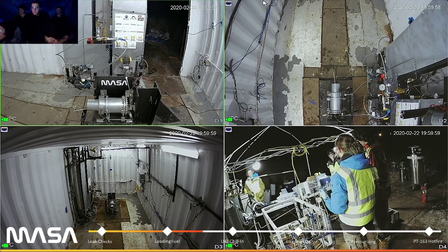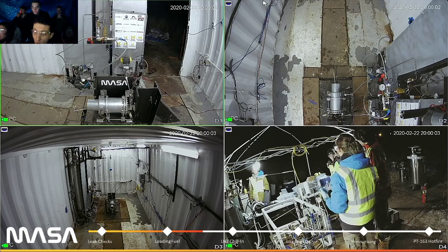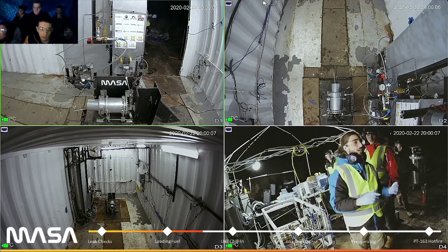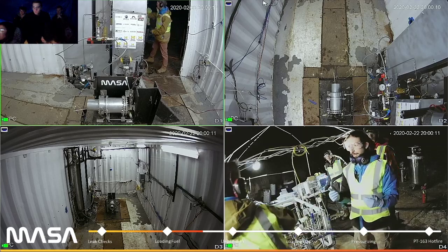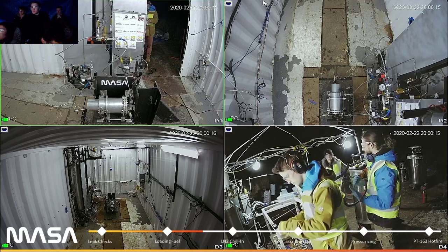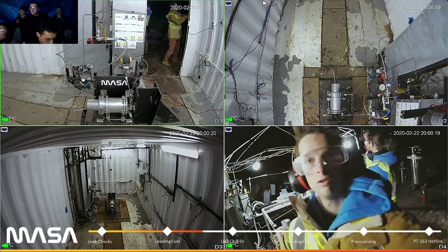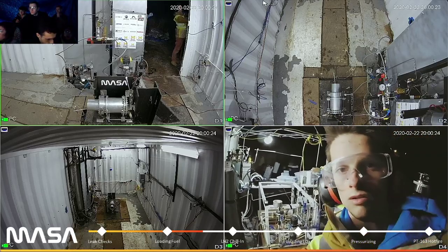Did you say that we're looking to get engine efficiency out of this test? It still needs to figure out what our injector efficiency is. Oh, sorry. Yeah, I didn't answer the first part. Basically, by looking at the pressures throughout the entire system, through the tanks, mainly the pressure the injector's being fed, the pressure we get in the combustion chamber, and the thrust we get, we can compare that to what we would expect, and then from that determine what our injector and combustion efficiency is.